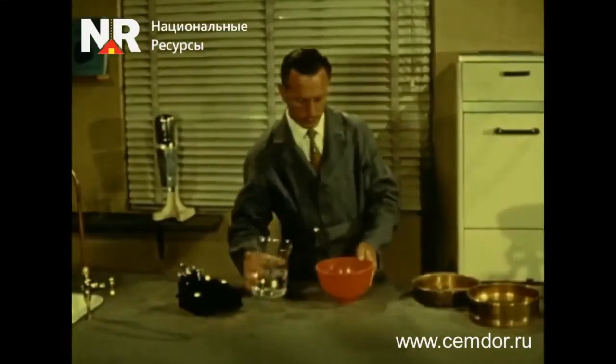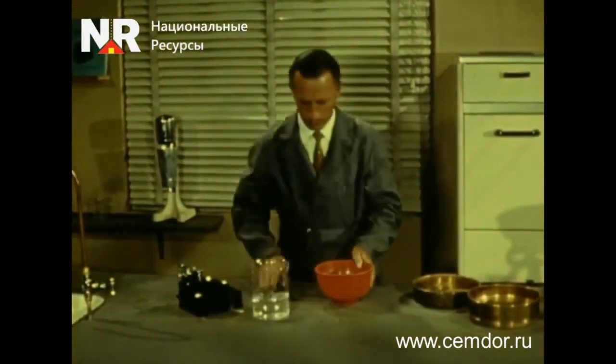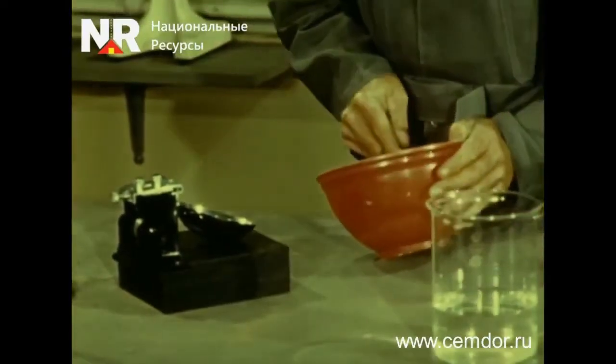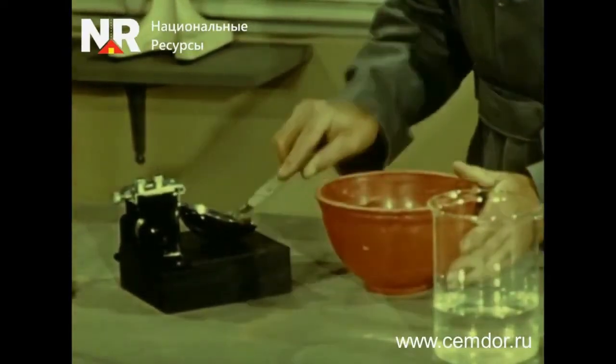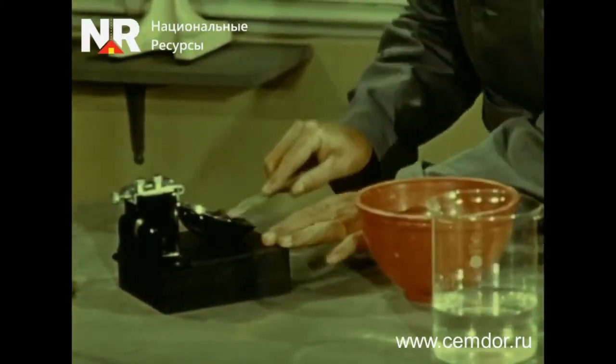The next important characteristic of soil is its plasticity. It is characterized by the plasticity index, which is the difference between the moisture content at the liquid limit and the moisture content at the plastic limit. To determine this, the soil is crushed and mixed with water to prepare a paste-like mixture.